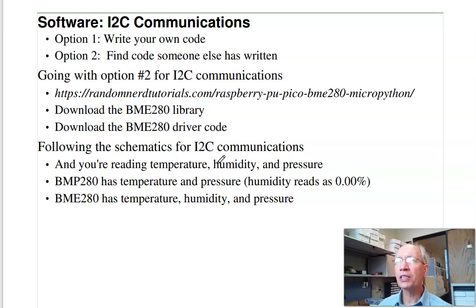To do that, you need to go to that website, download the BME280 library, download the driver code, and then follow the schematics, basically the previous one, run the driver code, and you're good to go. You're reading temperature and humidity.